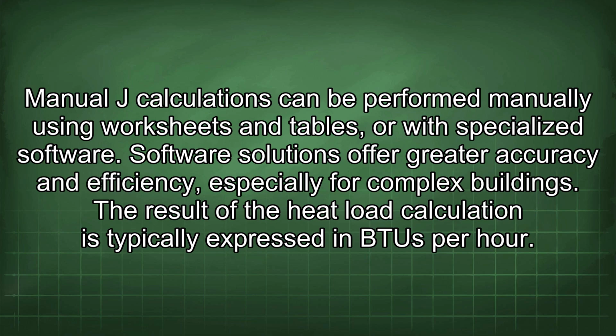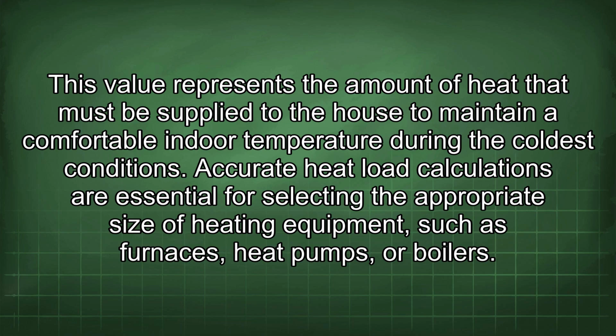The result of the heat load calculation is typically expressed in BTU per hour. This value represents the amount of heat that must be supplied to the house to maintain a comfortable indoor temperature during the coldest conditions. Accurate heat load calculations are essential for selecting the appropriate size of heating equipment, such as furnaces, heat pumps, or boilers.